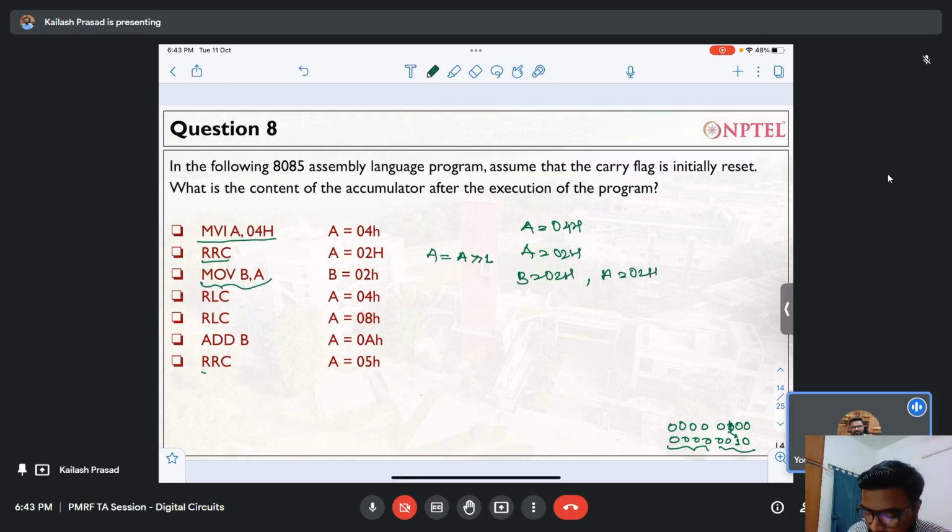Then you're doing a left shift. Whenever you write this kind of instruction, these are called implied instructions. Implied instruction means the instruction and the address have been implied on it. Here it means that whatever is the value of the accumulator, you shift it to the left. What is the value of the accumulator? It is 2. So the accumulator has to be shifted left.